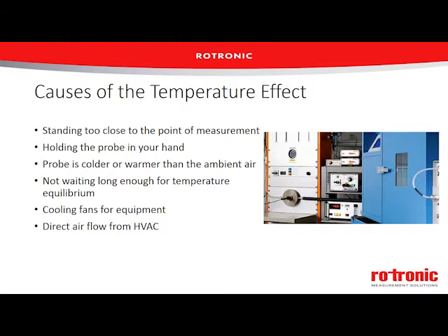And we're also, when we breathe, breathing out very moist gas. So that will have a direct relative humidity effect on the sensor, even beyond the temperature effect. We want to make sure that the probe is not colder or warmer than ambient air. We see the example of our bodies potentially causing that effect. But it can also come from taking the probe from one environment to another.